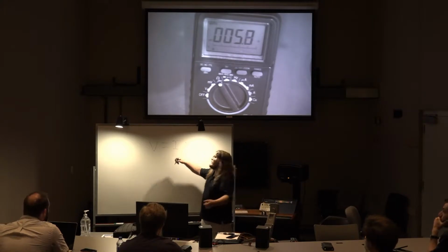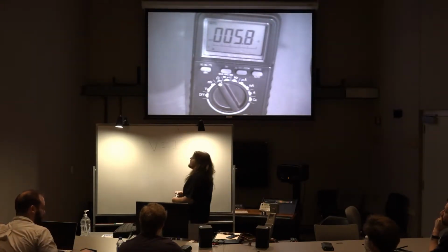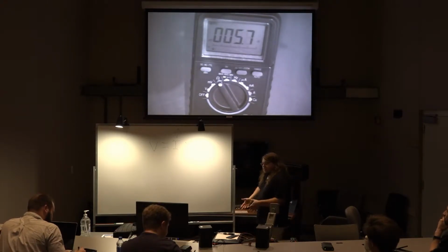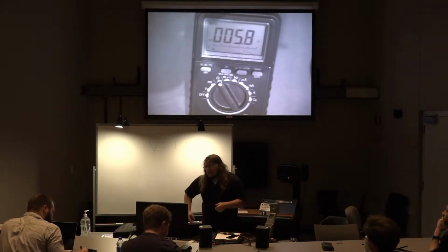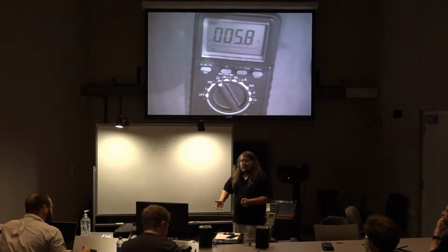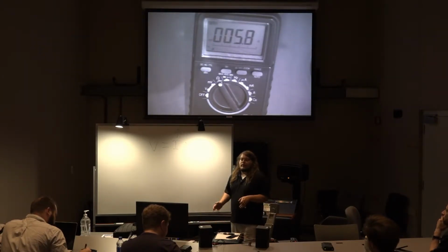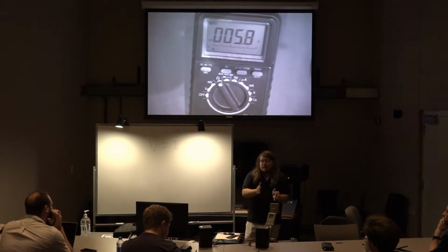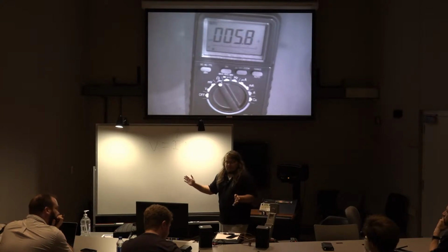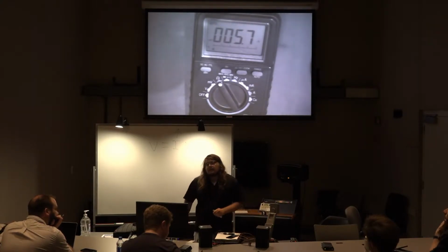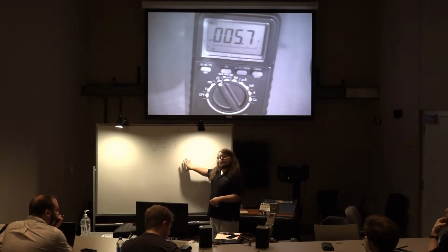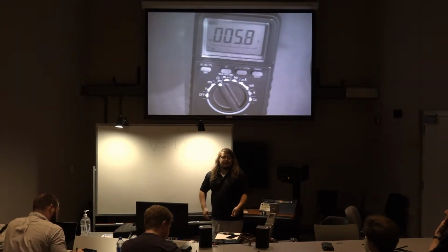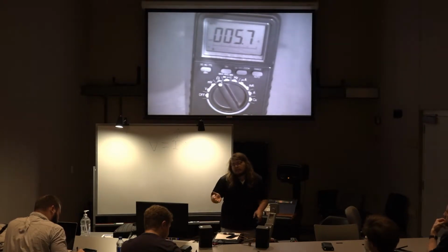It goes up, right? Remember this balancing act before? Okay, so now we've kind of puzzled out or teased out the fundamental problem with thinking that we can just take parallel circuits and continue to split them into infinity, right? As we can see, the more things we put in parallel, the resistance actually goes down. Kind of counterintuitive, right? We have more speakers.